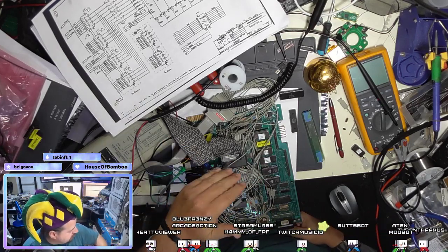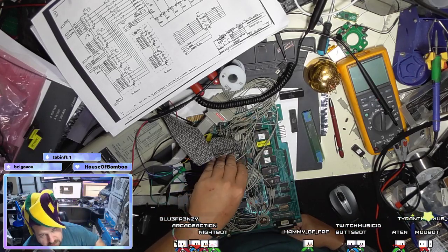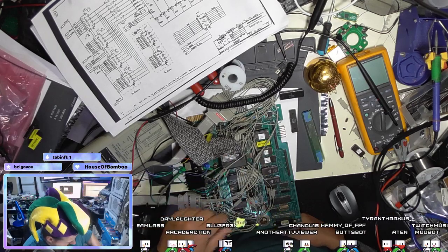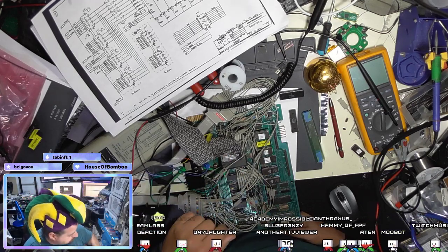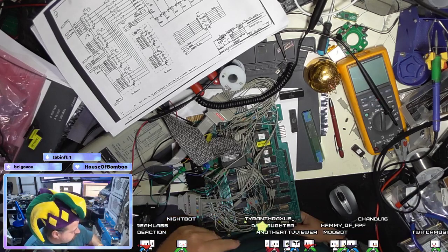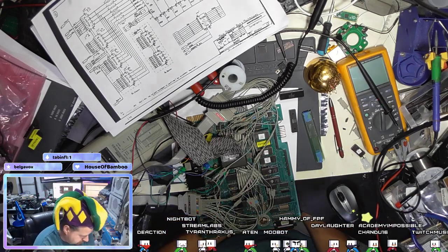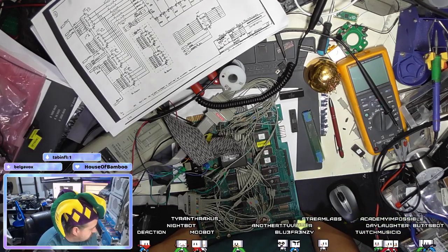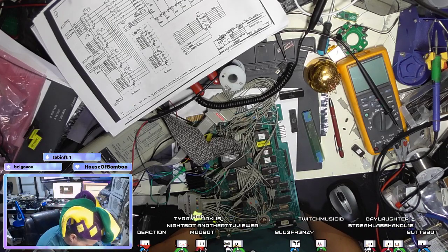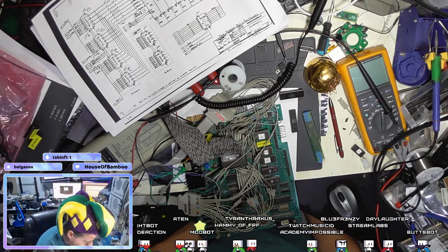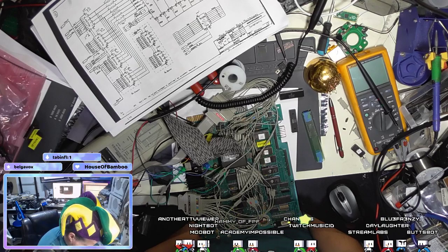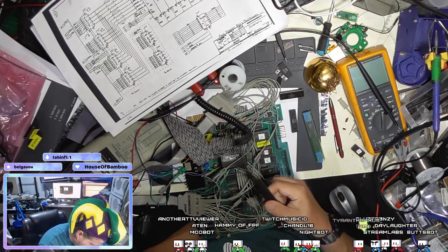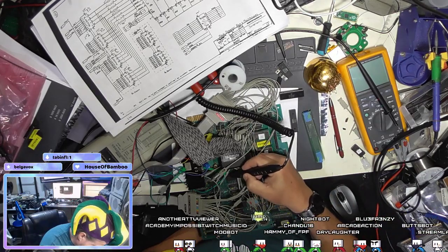Right now I'm reading and writing and testing the RAM at 8000 to 8FFF, and it is verifying that that circuitry is working, just like when you turned the computer on back in the day and it would count up the RAM. And RAM tests fine, which is actually a miracle that all the RAM on this board has tested okay. But it is not initializing the video.